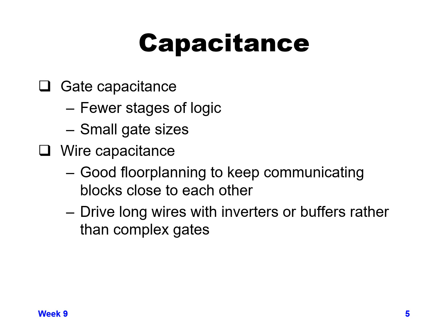But if you have a fairly low capacitance receiver and you're doing a set of logic and you know you don't need to buffer it up, instead of using multiple stages of logic, you might be able to get away with less gate capacitance by using fewer stages of logic if you can optimize it.